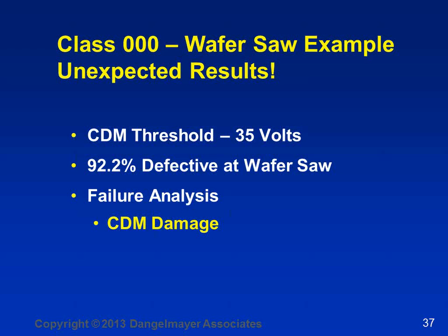In this example, the problem was resolved by adding CO2 bubblers to the water, which helped, but did not solve it. It also required a change in blade, saw material to reduce the frictional charging, as well as the speed of rotation and depth of cut. So there were several variables that had to be adjusted to prevent this problem from occurring.